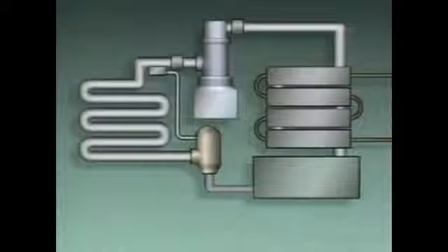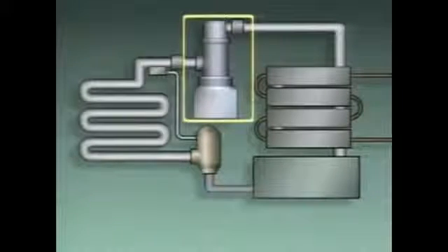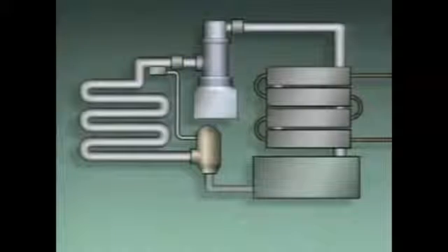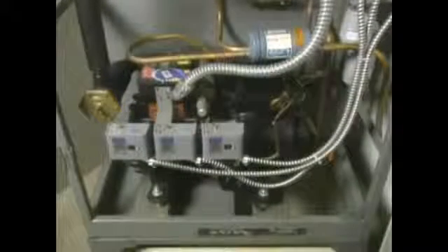To operate properly, a refrigeration system must control refrigerant pressure and flow. In a system that has a reciprocating compressor, the flow of refrigerant is produced by the pressure exerted on the refrigerant in the compressor. Some types of refrigeration systems maintain the desired amount of cooling by cycling the compressor on and off. This controls the amount of refrigerant that flows to the evaporator.